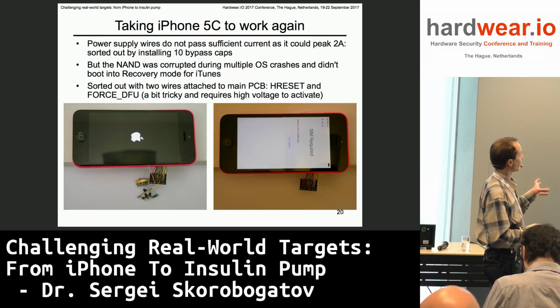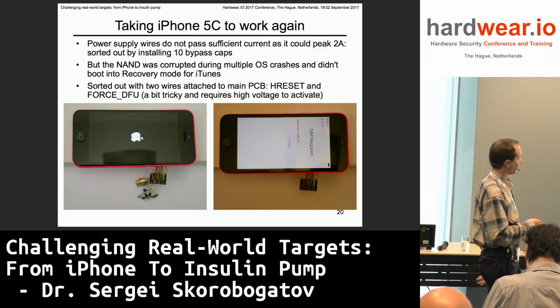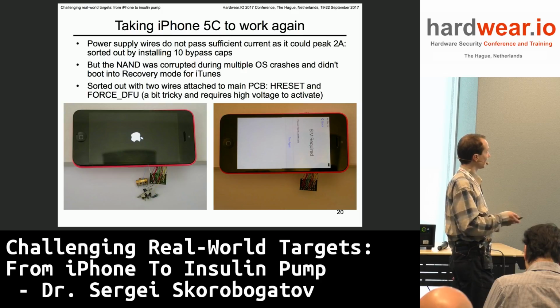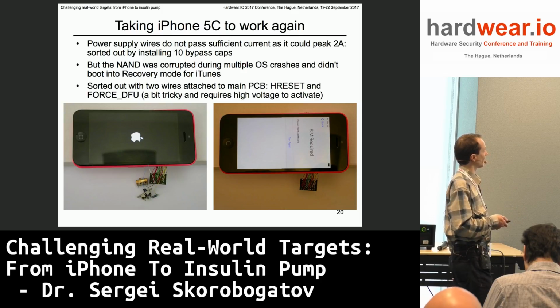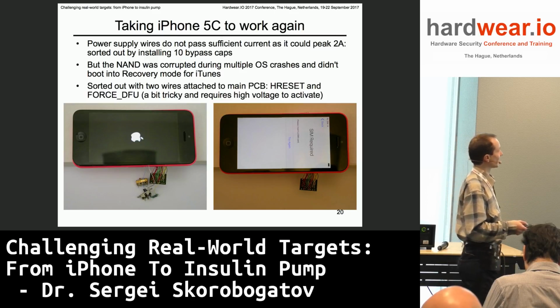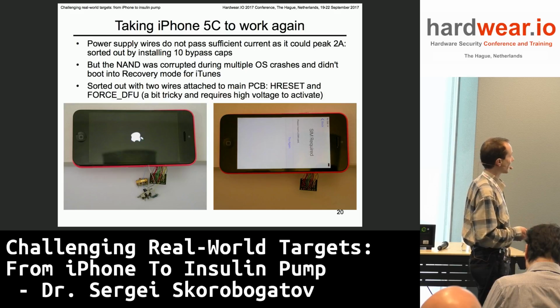But because during the boot process the NAND was corrupted, the iPhone OS does not restore it back to the original state. So I had to also wire reset, and the wire that forces the CPU into recovery mode, outside, and then force the CPU in hardware to go into the restore state and bring back the iPhone to the original operation.